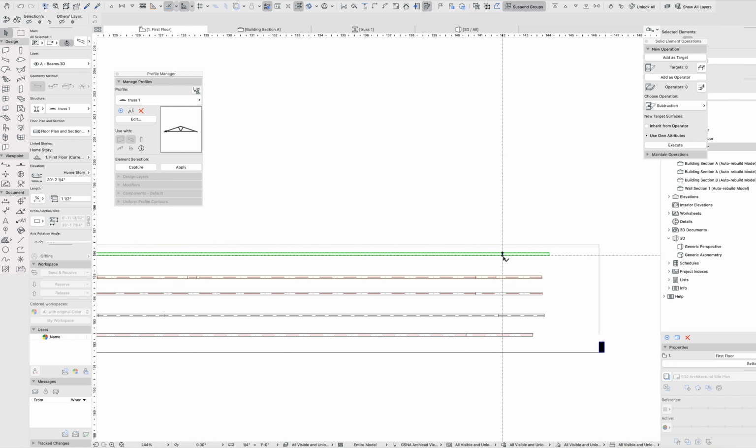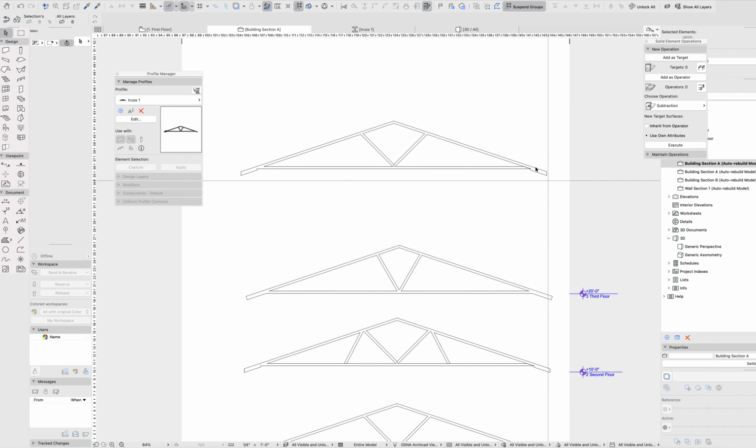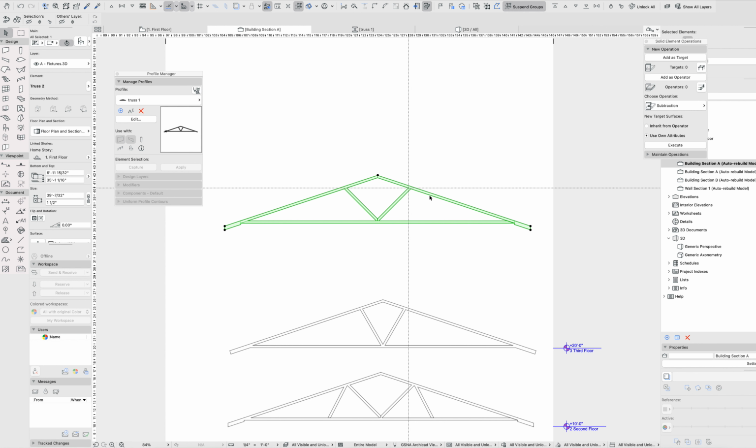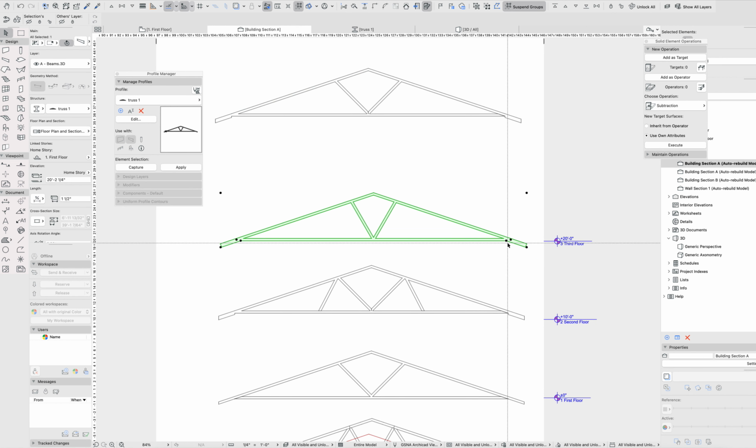This wants to be a beam that's an extrusion along this length, and depending on how it's classified and how it translates through, I've seen them either not show up at all or show up incorrectly because of their sort of perpendicular extrusion. But as far as basic modeling goes, there are ways to work around that with IFC translators. As far as basic modeling goes, this is a great way to just drop a beam in and start extruding it out. Oops, sorry, this one right here.